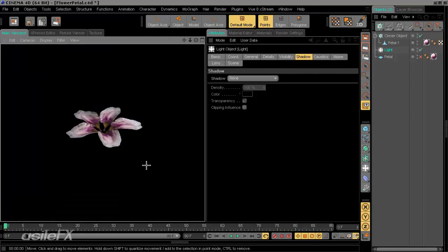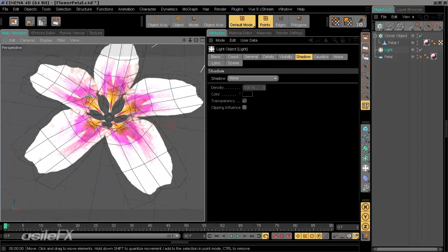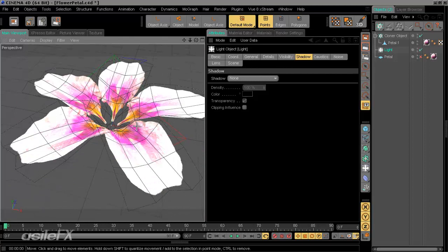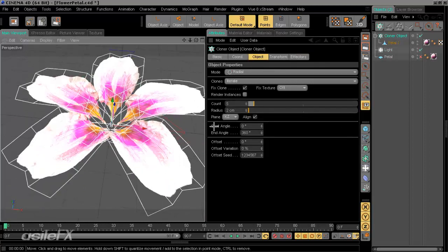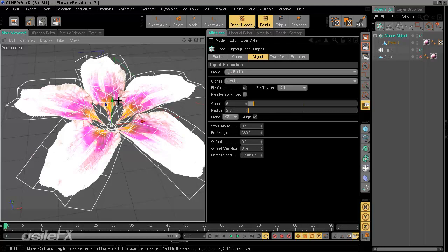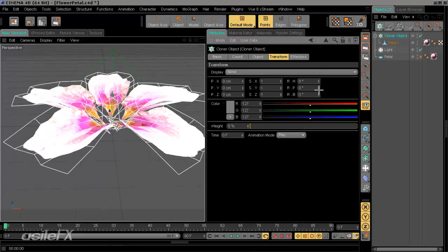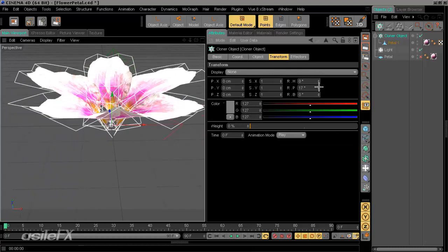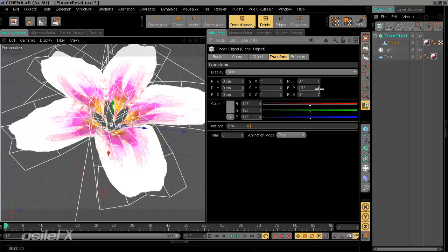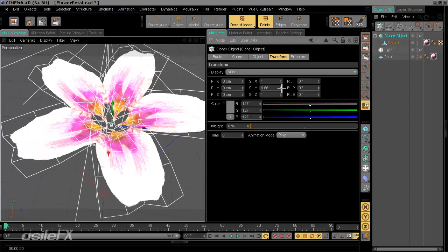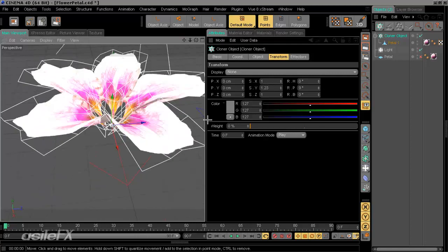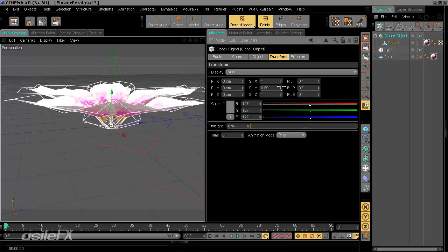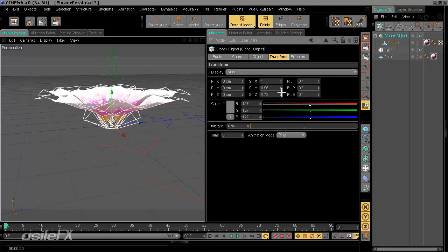So now what I'm going to do is create a base for the flower. Also add a little bit of randomness to the petals and the way they are going to kind of bob up and down or adjust the pitch. We don't want to do it with every single one, although one easy way to just adjust all of them is by going to the transform. And then if you also want to make modifications to the curvature, which you can do by modifying the Y scale, we'll kind of cup it out a little bit more and stretch it, make these nice little modifications.